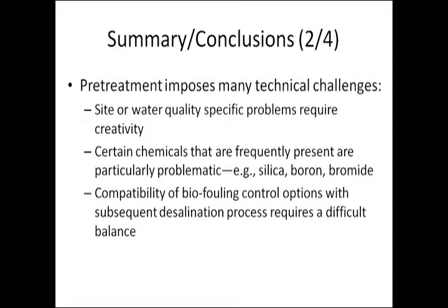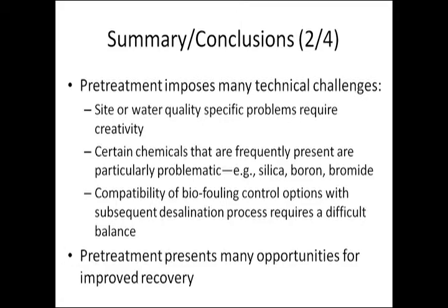Pretreatment, I think, has many technological challenges. The site-specific problems require a lot of creativity in solving them. Certain chemicals are frequently present and particularly problematic. Silica, boron, bromide are ones that I'm kind of conscious of. Compatibility of biofouling control options with subsequent desalination process requires a difficult balance. I think that there's many opportunities for improved recovery here. If you do the pretreatment right, you can get much better recovery, and that's very useful.